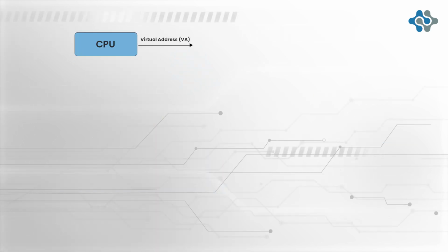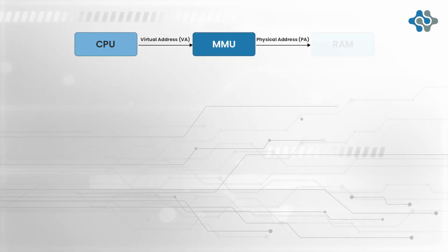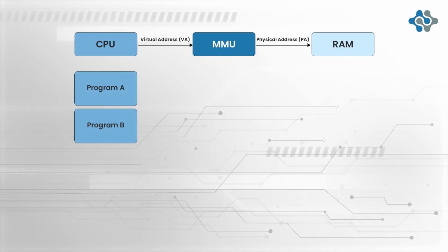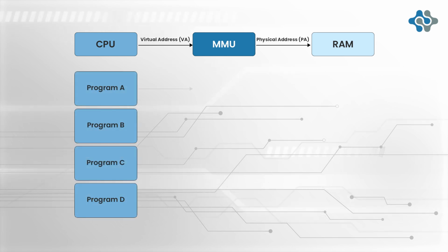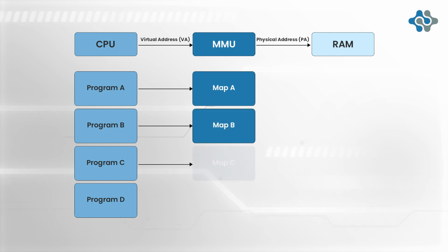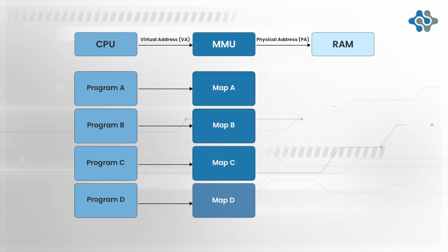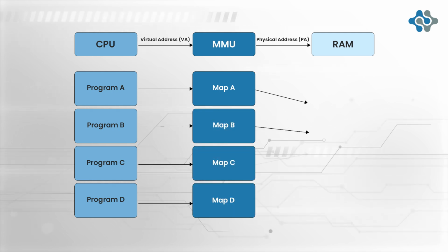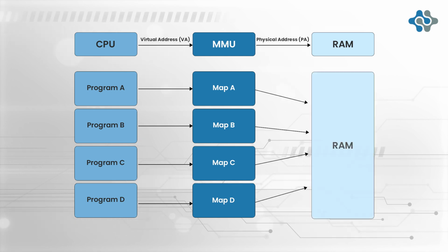Unlike most MCUs, MPUs have a memory management unit. It allows for virtual memory and process separation, meaning one application crash is less likely to take down the whole system. It enables running complex operating systems that require more resources at the same time, opening up a world beyond simple schedulers or basic RTOS kernels. So what are these options and how do you choose?